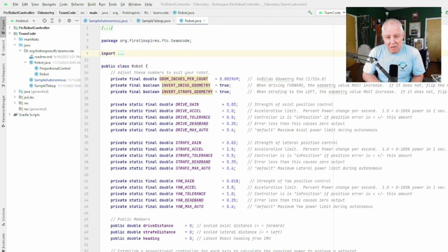So it will close on the desired position or desired angle without the addition of an integral element in our controller, because it's already built into the velocity controller of the wheels. These constants that we're using here to initialize each of the controllers, I'll talk about later when we actually talk about the controller, but suffice it to say that you can tweak each of your axes depending on your robot's performance. You can make it more responsive or less responsive to your heart's content.